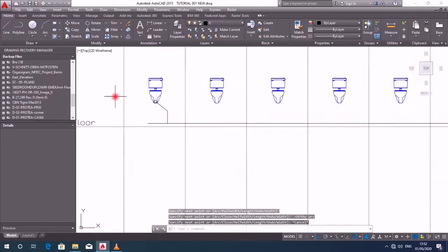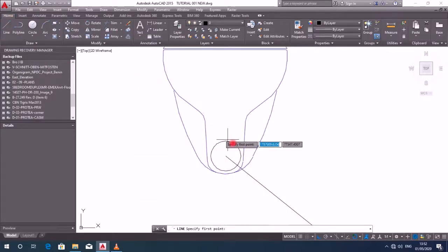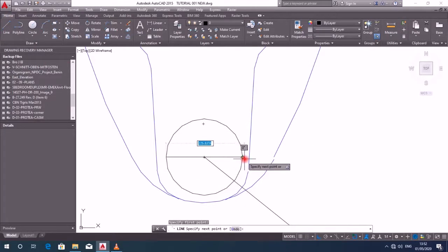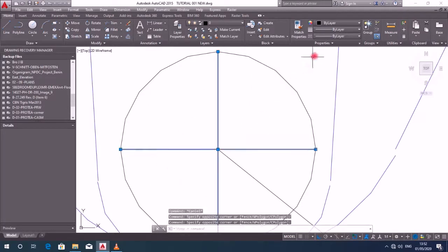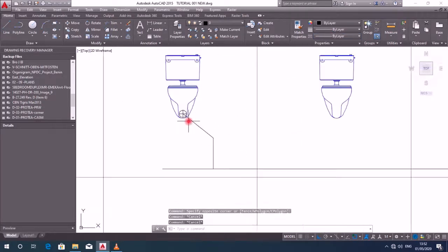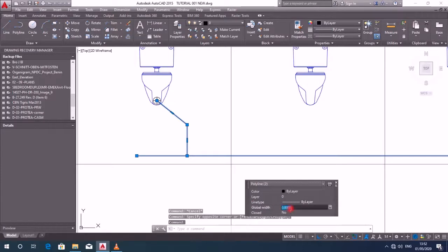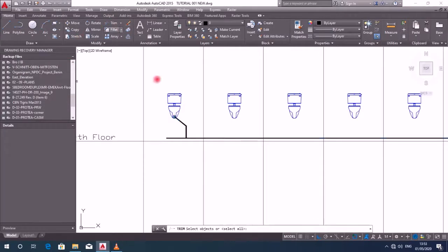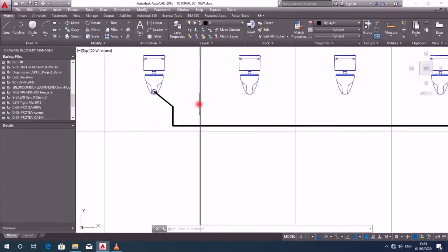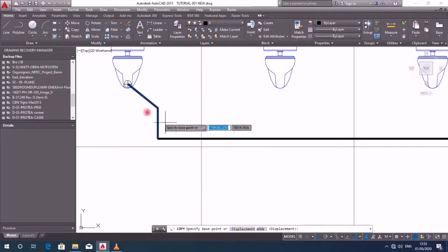We'll start putting our connections to show that it's a diameter. You can draw the line. Okay, I'll change it to center line, to show us it's a diameter. So we're going to change the thickness of this line. For this purpose, we are going to use global width. But in normal practice, we are going to put everything on a layer and give it a specific line width.